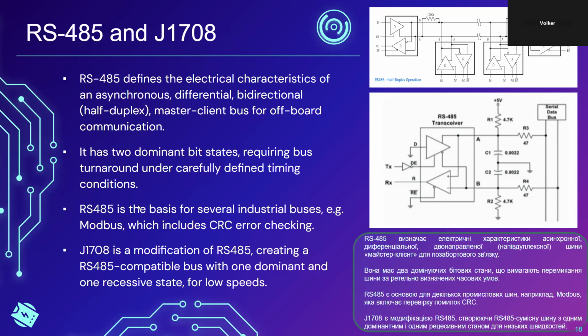It's not really a problem. It used to be a problem with older microcontrollers because the UART implementation was not telling the software when the last stop bit was clocked out. The UART implementation was telling the software when the transmit register was empty, but the transmit register was empty before the last stop bit was clocked out.